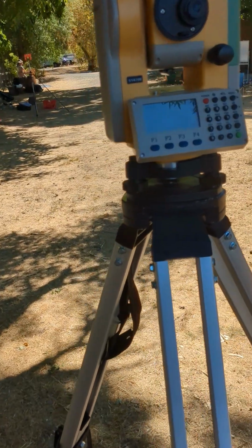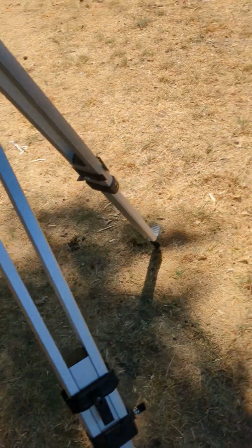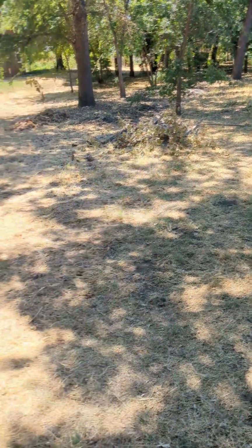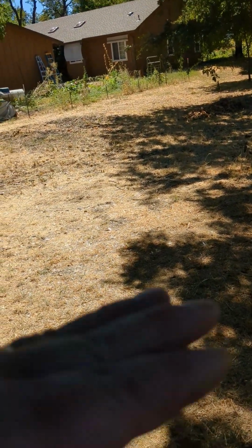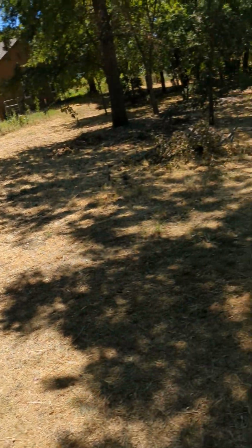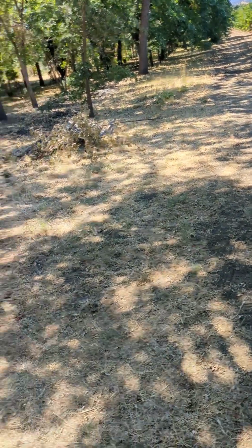Again, you could use this as a point. You now know the NEZ value of this point. You could walk this down the field there and point it at this point. Use that as your NEZ reference to do the rotational calibration, and that will get you to transform this location over to that location so you could make local measurements over there.